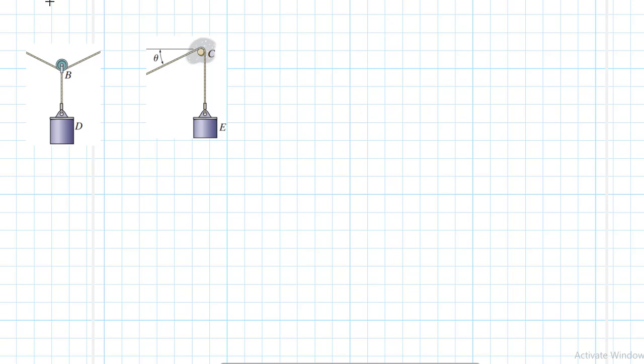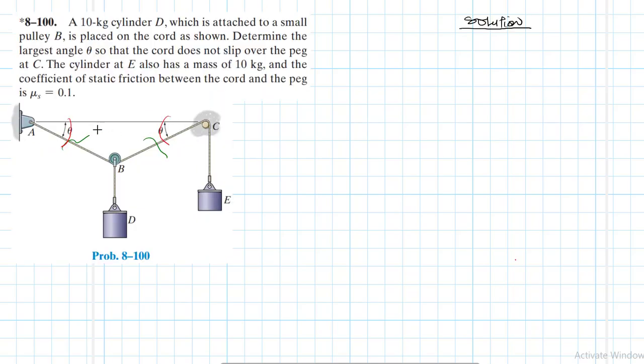Here we are. So let's now add some meat to this skeleton. Of course, we are going to have tension, and we call these cables as having tension TB. We expect to have the same tension in this because this is a continuous cable that is going over the pulley and there is no friction over this pulley. So we expect the same tension throughout, and it will have the same angle. These angles are already given, which you've seen here. They will have the same angle because this cable will tend to realign itself so that it has the same angles and the same tension throughout.